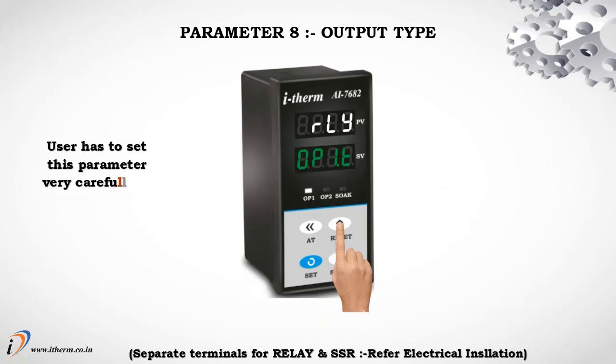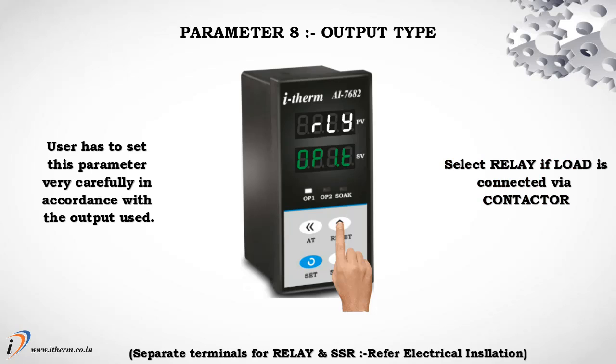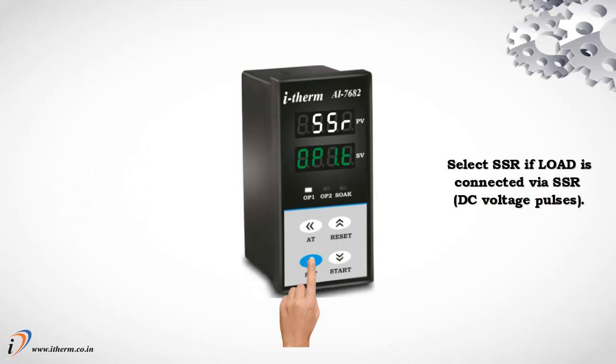Parameter 8, Output type. User has to set this parameter very carefully in accordance with the output used. Select relay if load is connected via contactor. Select SSR if load is connected via SSR.